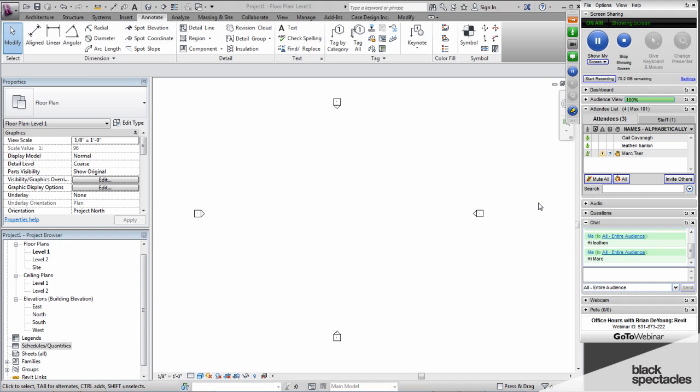So typically we'll have a core work set, an exterior wall work set, an interiors work set, and then we also, quite frankly, divide up our models as well. So that helps us even further. We'll have, say, a tower model with one or two people working on that, then a podium model with one or two people working on that. A combination of dividing up the project into identifiable pieces like that and separate models, and then dividing up those models into work sets, works fairly well and prevents people from stepping on each other's toes.